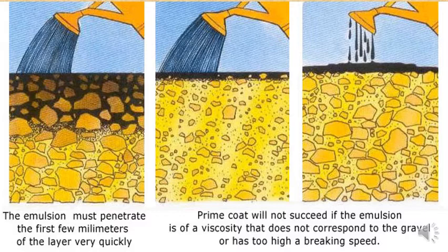If it's too high a viscosity, it's going to clump on the surface. And then it's going to wash away as soon as you have cars driving over it, because bitumen in and of itself has no strength. But if it's the right amount of viscosity, it's going to mix in with the aggregate just the right amount, and that's going to create a nice strong and waterproof surface on the road.